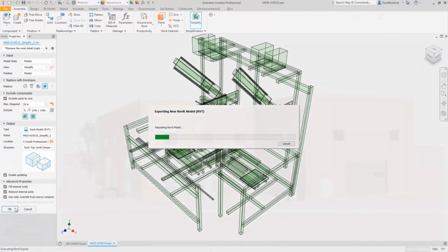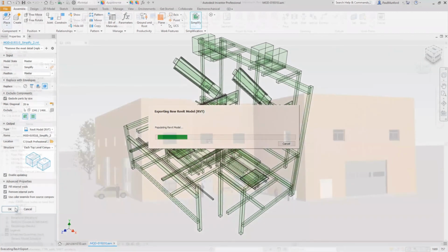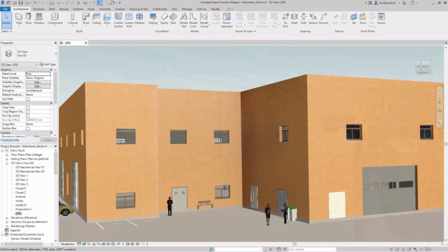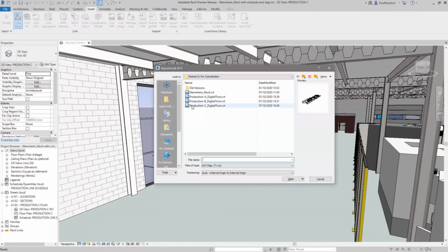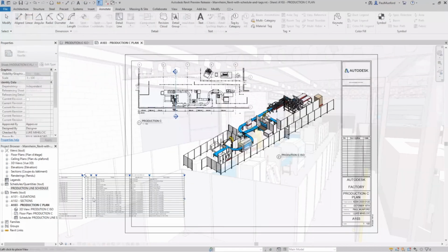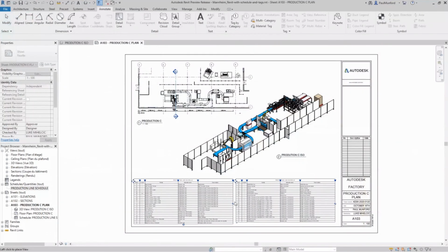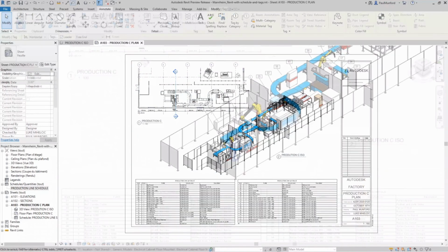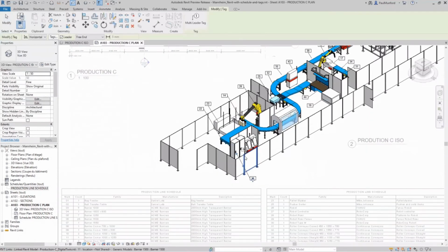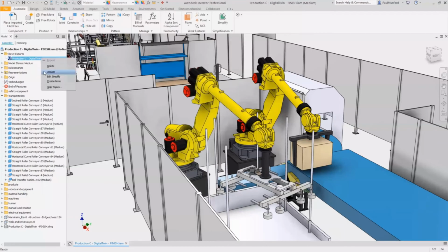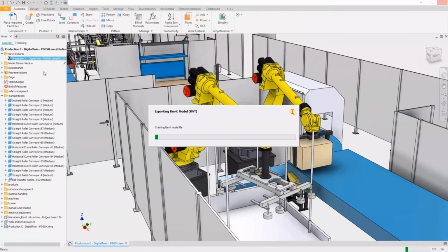So quite a number of really beneficial little tools there for working within Revit and linking that to our design process. So yeah, very, very handy little tools there. I think you'll agree that linking that straight into Revit is a very beneficial thing. So we can take that update of the Inventor model. So again, this is fully associative, and we can use that preset file to export the model again and to update that in Revit or coordinate it with a BIM 360 situation.